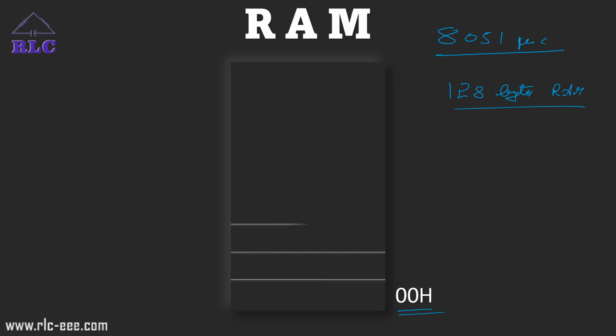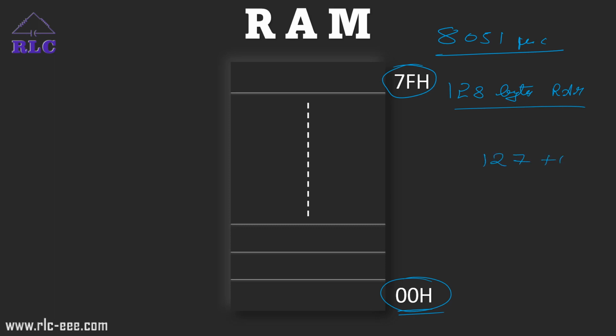The 8051 microcontroller has 128 bytes of RAM. It has an inbuilt 128 bytes of RAM. The memory locations start from 00H to 7FH. That means 7F is 127, plus 1, which gives us 128 bytes.